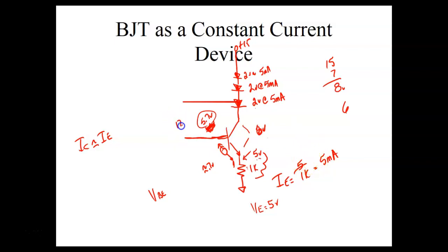So if I had 12 volts and I wanted 15 milliamps over here, then I would choose a resistor that would drop what? Yeah, it'd drop 11.3 volts at 15 milliamps. And then of course we would choose a resistor. We'd either decide to go up or go down depending on the current demand of the load. LEDs, when we say 15 milliamps, you could put 10 milliamps through it, it just wouldn't glow as bright, right?